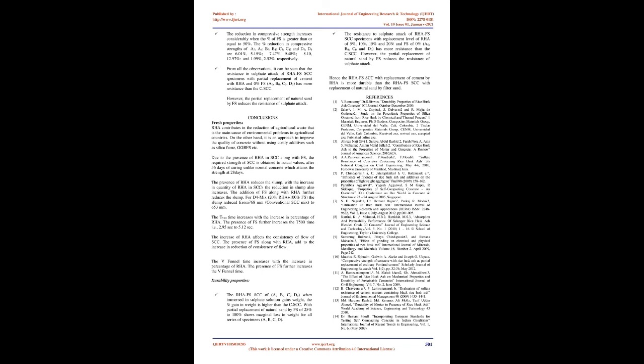The strength reduces by 0.35%, 5.15%, 0.79%, 9.48%, 5.21%, 12.97%, 4.38%, 2.52% respectively. The reduction in compressive strength increases considerably when the percent of FS is greater than or equal to 50%.